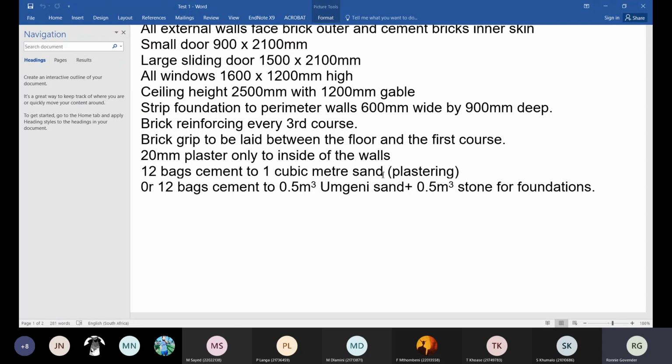So I said, if you took the total volume of plaster you require, let's say for argument's sake, you need 1.2 cubic meters, you divide it by 1.42. That is the magic value if you're working out how much sand only. That means that you want to use 0.85 cubic meters of sand and 0.35 cubic meters of cement to get 1.2 cubic meters.